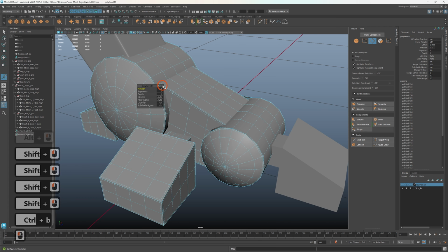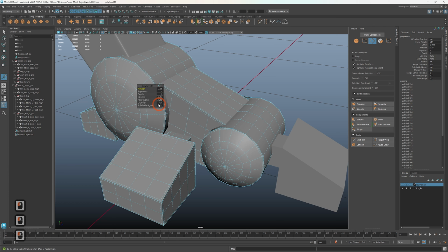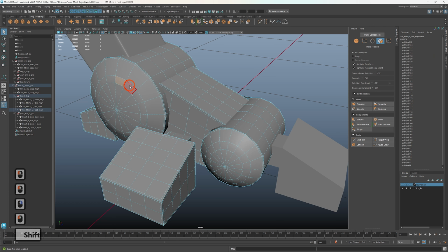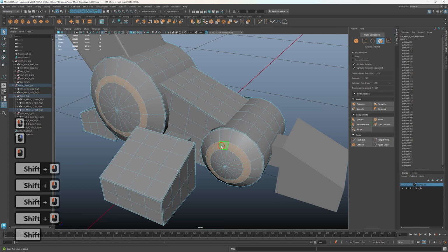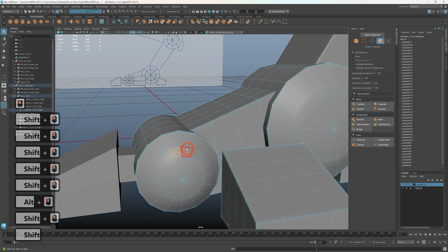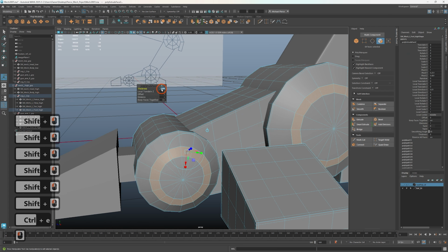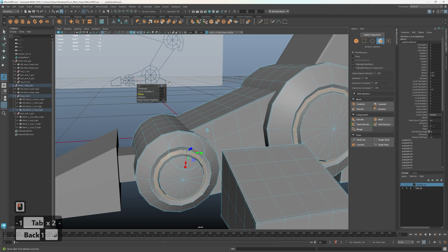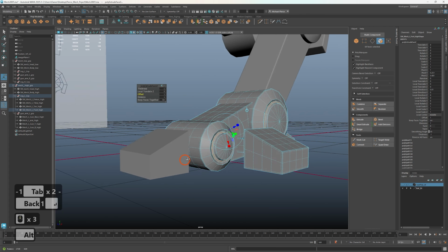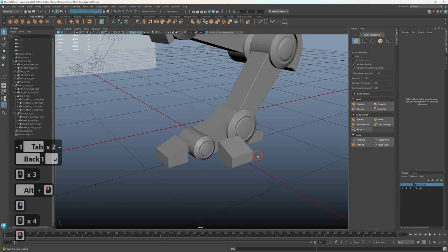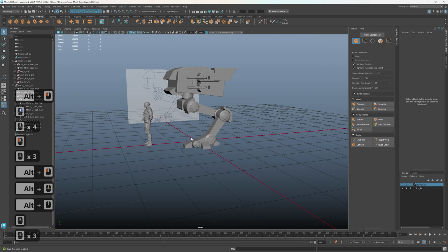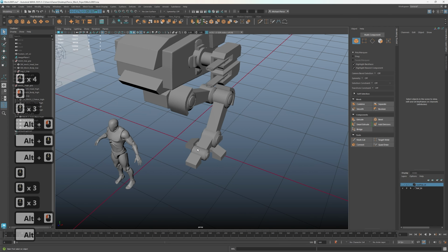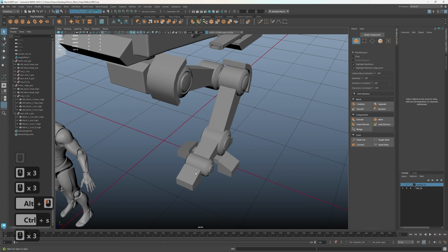Bevel. And then I'll paste in my attributes. Go to faces. Grab my faces here. Control E, -1 on the thickness and 1 in the offset. That way it gives a nice little effect. There we go. Nice. All right. I'm going to save at this point.